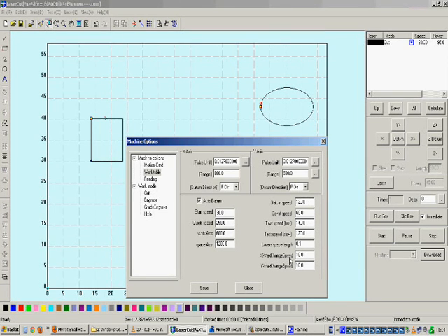The laser space length and the maximum X and Y axis change speeds will not be used so much, so do not change these values at all. And also work acceleration and space acceleration are the acceleration values while the laser head is working or moving.